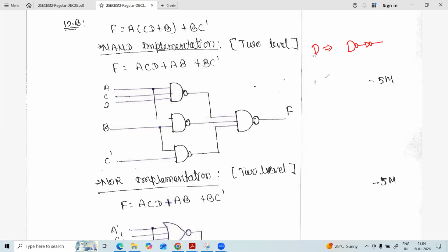Whereas whenever we have an OR gate and we are going to convert it into NAND gates, here we apply the bubbles at the inputs. When a bubble is applied at the input, here also we can add the inverter. If the number of inverters on the same line is even, then both will be cancelled. That is the logic we are going to use.